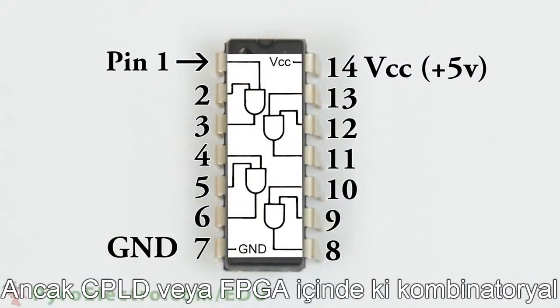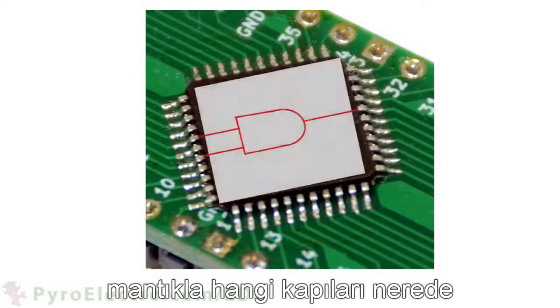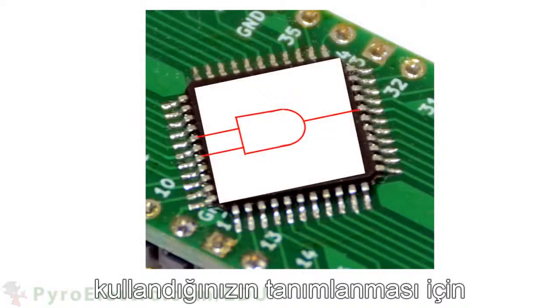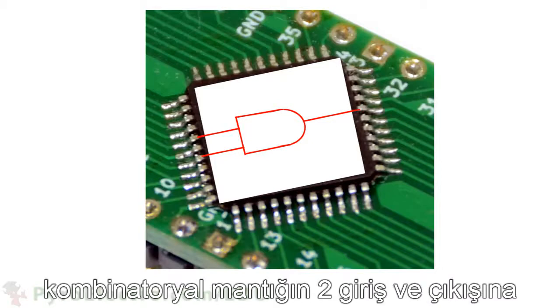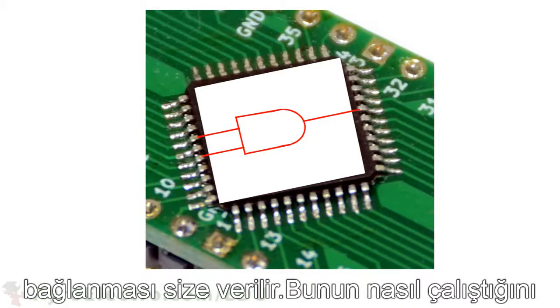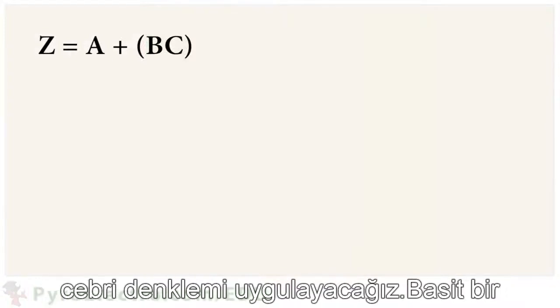But with combinatorial logic inside of a CPLD or FPGA, you are given the power to define which gates you are using where, and which pins of the CPLD should connect to inputs and outputs of your combinatorial logic. To show how this works, we'll implement a Boolean algebra equation inside of a CPLD.